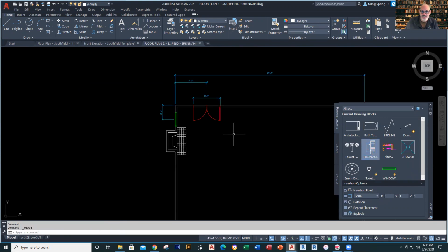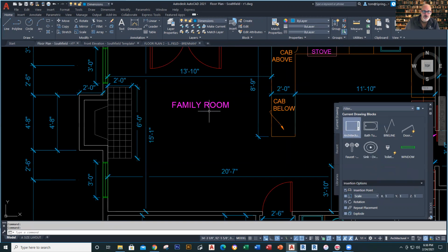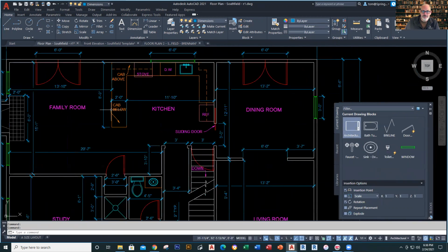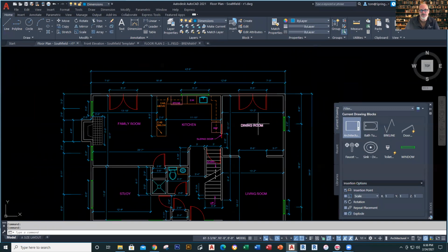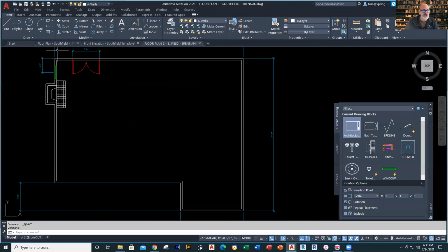Okay, I just used my basic commands right here. We've got it together. There's other things out here that would require more thought and so forth. But as it is right now, it's going to be placing walls and so forth, which are pretty straightforward. One thing I'm going to do right now, I'm going to go ahead and put one wall in here at 13'2" away from here, just to give me a basic right here. Because a 13-foot wall, I'm just going to offset this one 13 feet too. So I'm going to offset this wall 13 feet too.